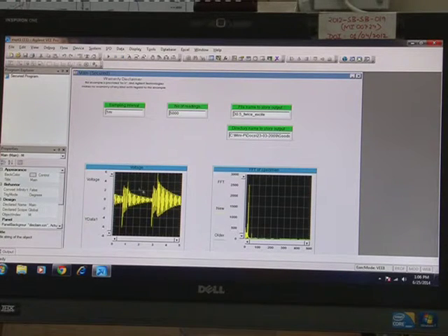So, you can see the impact of the hammer is producing voltage response in the PZT patch. Now, why we are getting two different responses here is that in the 5000 readings, during this 5 seconds, the hammer has hit the cantilever beam twice. That is why we are getting two impact responses, and this plot gives the FFT response of this voltage.